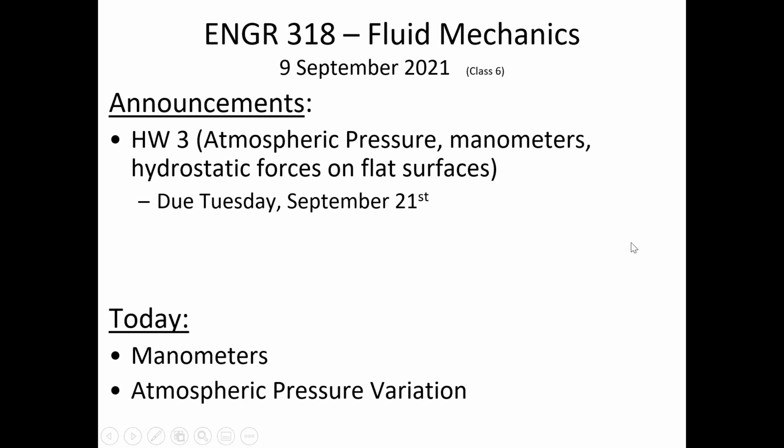All right, manometers. Now, who can remember when it comes to a piezometer? Let me just sketch a piezometer on the whiteboard here. Let's say we had a pipe and there's water flowing through the pipe and it's pressurized. And so one way of measuring the pressure is you just cut a hole and water sprays out all over the place. But then instead of allowing the water to spray out everywhere, what you do is you put this vertical conduit, and then the water level rises to a certain height.